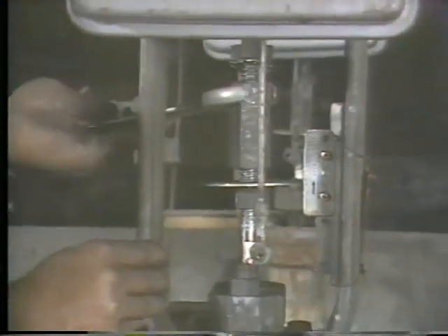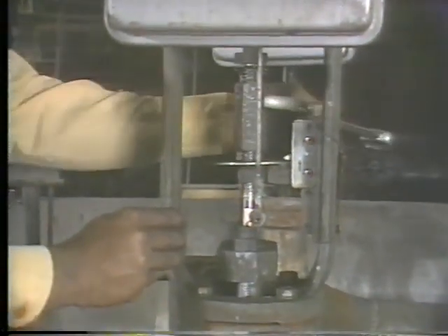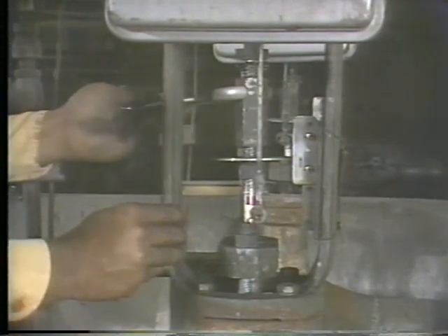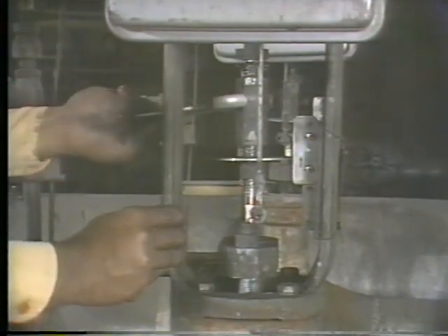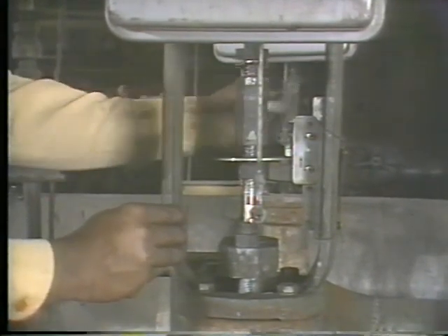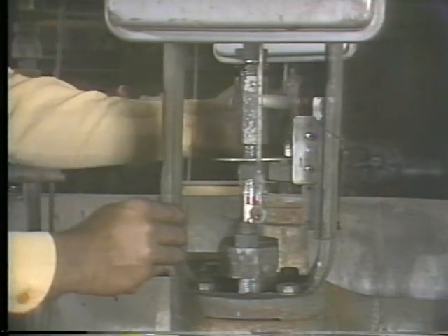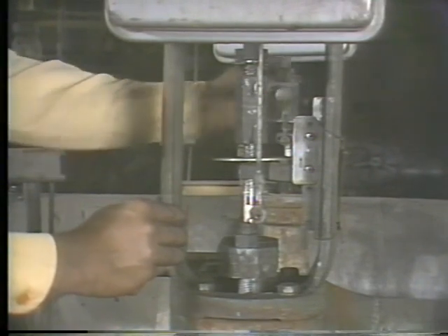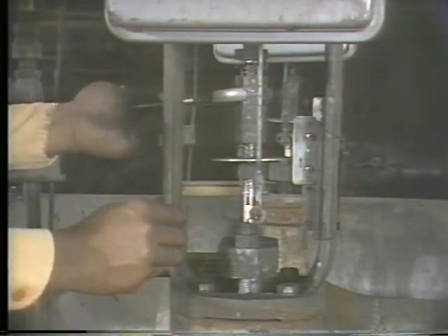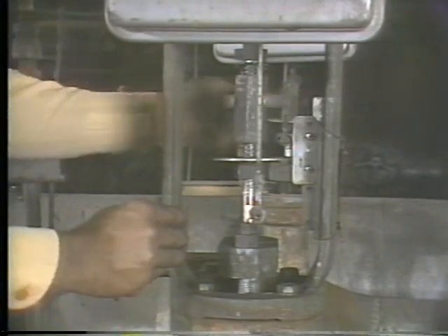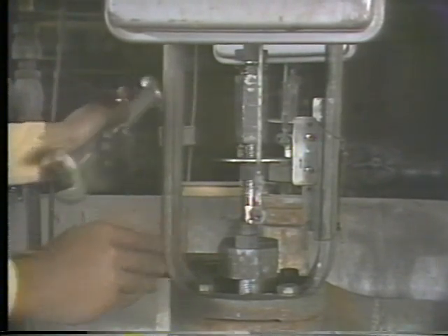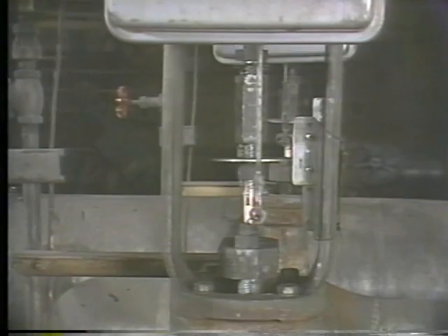Next, we want to raise the valve up so that the indicator plate is lined up across from the high scale marking. To do this, raise the long hex nut until the bottom edge of the nut is lined up with the high scale marking on the travel indicator scale. As you do this, the long hex nut screws onto the actuator stem, securely connecting the actuator and valve stems. Be sure not to move the small hex nut that is supporting the travel indicator plate across from the low scale mark.